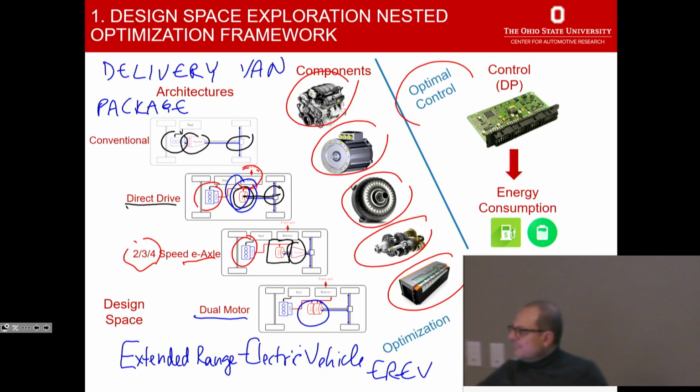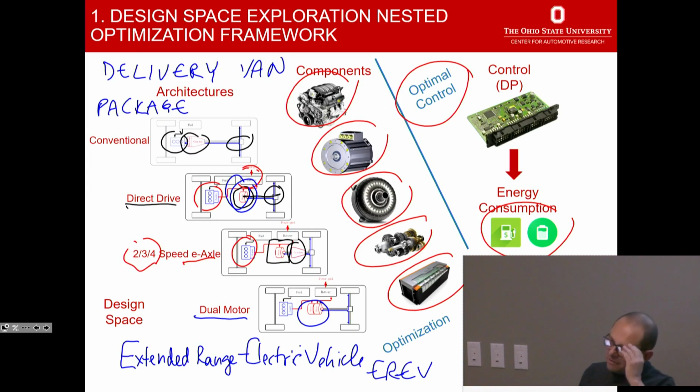Of course, I'm going to have to come up with an energy management controller, okay? And finally, I'll consume the energy, I'll calculate the energy consumption. And by the way, the energy consumption, in this case, I have to be careful how I evaluate it because there will be fuel for the engine, but at the end of the day, I have to plug in, so there is a cost to the electricity and eventually a CO2 emissions cost.